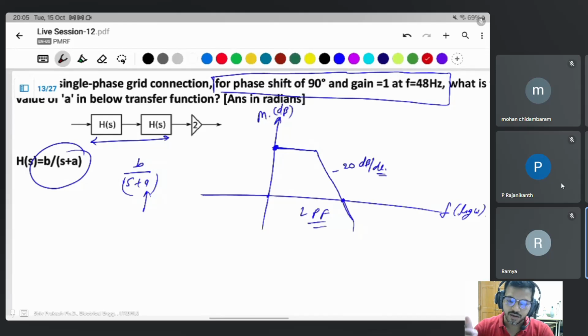Same thing: conversion of the three-phase AC signal to alpha-beta, then after you convert to the DQ system, because you need the reference in DC, the equivalent of DC. A single-phase system is also AC, so you need to track that system, and you need the equivalent of a DC system.